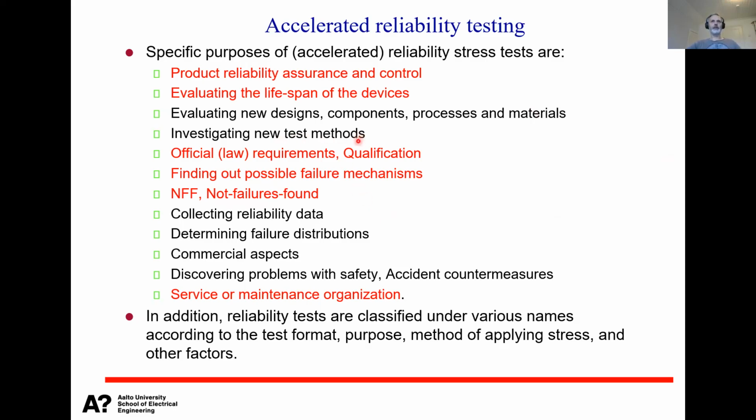Investigating or developing new test methods. Of course, for a company, this may not be that important, but for us, this was maybe the most important thing during the first decade of this millennium, because we were very much developing new test methods for lead-free solders, for portable products. So for example, which kind of tests you should develop in order to understand how handheld mobile devices withstand dropping. So this kind of mechanical shock loading test. That was really important for us.